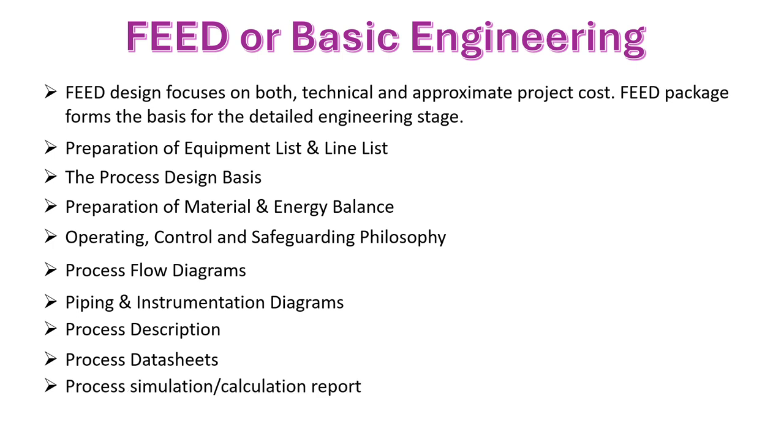In process simulations or calculation reports, we have to perform the calculations or review the simulations which are part of the basic engineering package. Also, we have to review the calculation reports or safety reports like DTA, screening calorimetry, DSC, or reaction calorimetry.